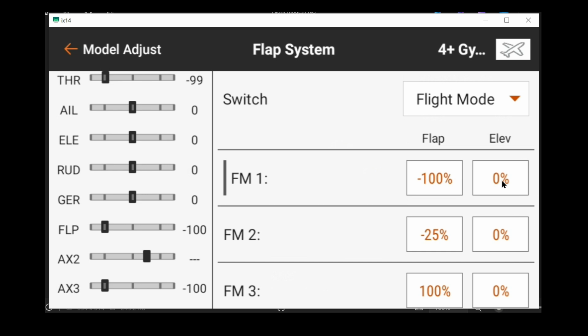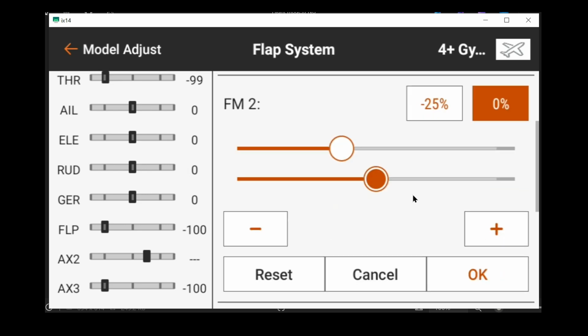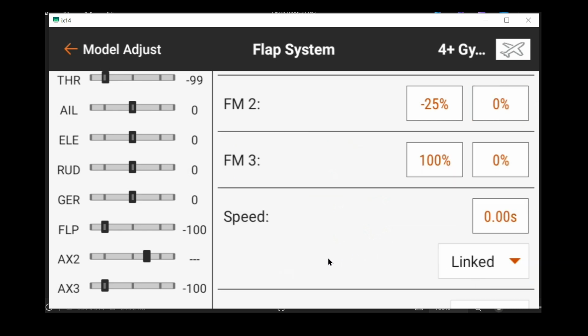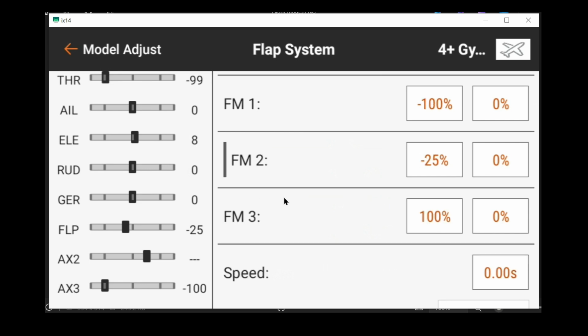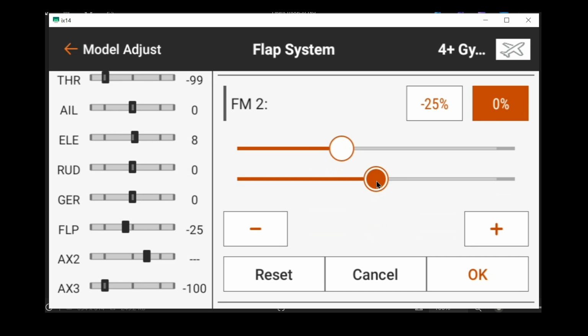and then this is full flaps. And I don't have to use these trims and play the guessing game on my elevator trim with the flaps down. I can use the trim levers. Now, once I figure out what the trim levers need to be set to, I can go over here and look and see which position I am in. I'm going to takeoff flaps. See, as I move the trim, I'll do it one more time, it says 8. Okay, that says 8. So what I need to do is change this to where it says 16.